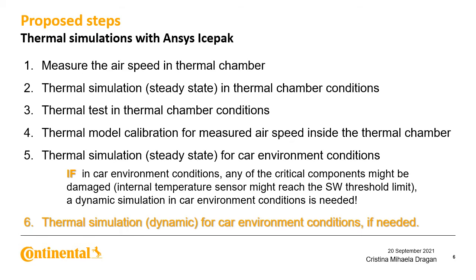The next step is to prepare and perform a thermal simulation, a steady one, in thermal chamber conditions. Perform a thermal measurement in thermal chamber conditions, and if necessary, calibrate your thermal model for the measured airspeed inside the thermal chamber. After having calibrated the thermal model, perform a steady state thermal simulation for car environment conditions.